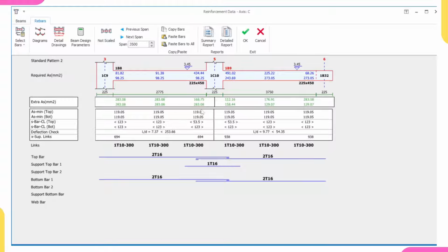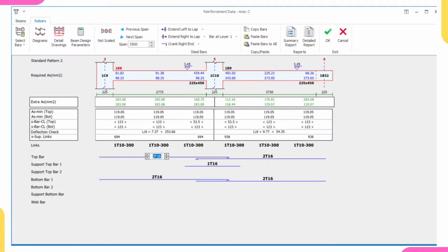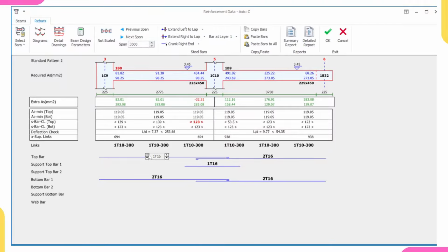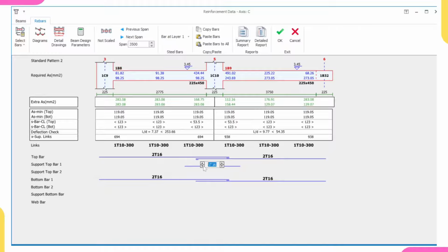So I'll just explain to you the failings in ProtaStructure and how to solve them. We have about 5 forms of failing in ProtaStructure. First, your beam can fail in bending. Bending means that you have not yet provided enough reinforcement to counter the bending moment. For example, assuming I'm having one reinforcement here, let me increase this one back to 2. Yes, assuming I'm having one reinforcement here.